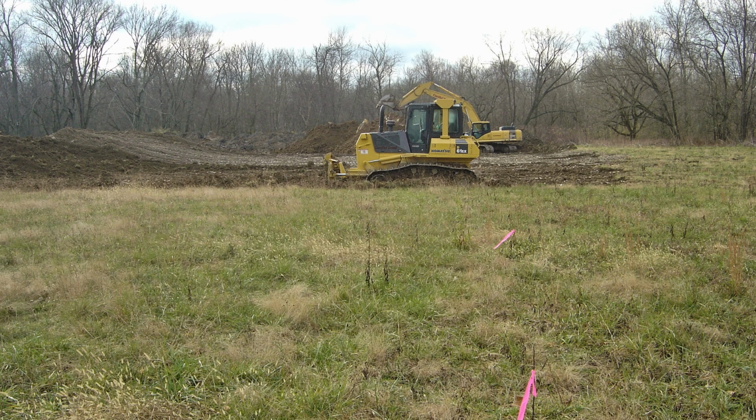Here the dozer removes topsoil from a 200-foot wide strip that extends inward from the pink flagging that was placed to mark the outer edge of the groundwater dam. Topsoil is piled in a windrow uphill of the pink flags. We would later spread this in the completed wetland.